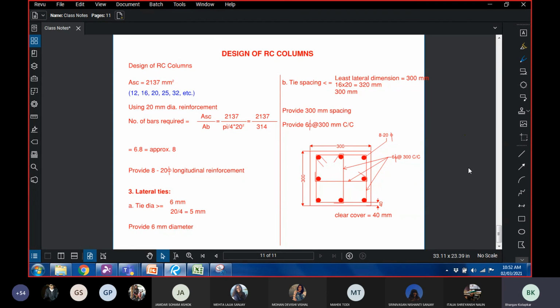It actually depends on whether you're designing it only for gravity or for earthquake zones 2, 3 or 4, where the intensity of the earthquake increases with increasing zone number. It depends on whether you are designing for gravity only, or for earthquake zone 3 or 4. But normally 50 mm should be a starter, 50 mm, 100 mm. All right.